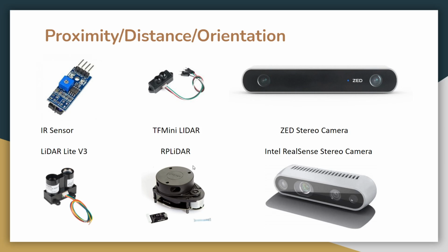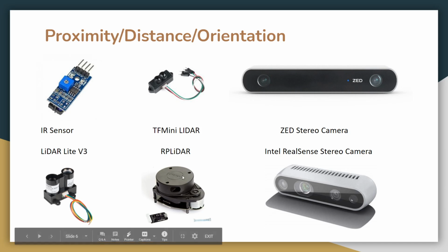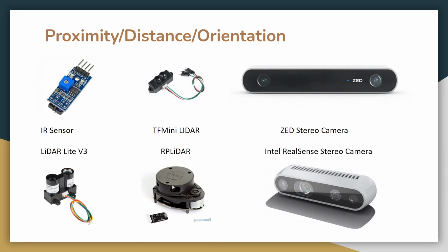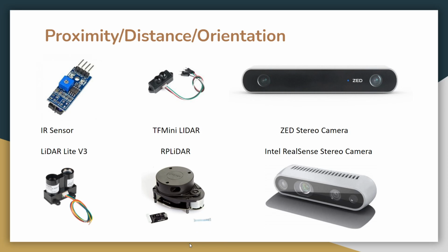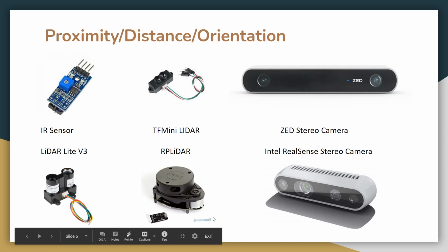So what some people have done to counter this is they've made a few sensors like the RP lidar, but they've also attached a translating joint kind of mechanism below it, such that during the whole rotation it pushes the lidar up and then brings it back down continuously, so that it gets elevation as well. But still, depending upon the speed of the translatory motion and how high the translation joint takes the lidar up, the elevation depends upon that. So that's one of the main drawbacks of the RP lidar.